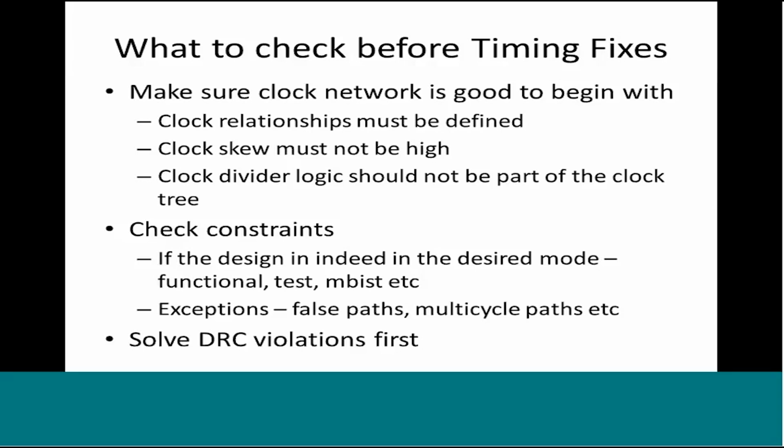This problem is called the correlation issue between your STA tool and the backend tool. Plus PrimeTime's timing engine is much more conservative. It lets you do so many things to make sure that you are on the conservative side when it comes to timing constraints. So all the timing reports that you will see will be in PrimeTime. You will make sure that all setup and hold timings, all recovery removal, min pulse width, and all DRC are meeting in PrimeTime. That is your sign off code.